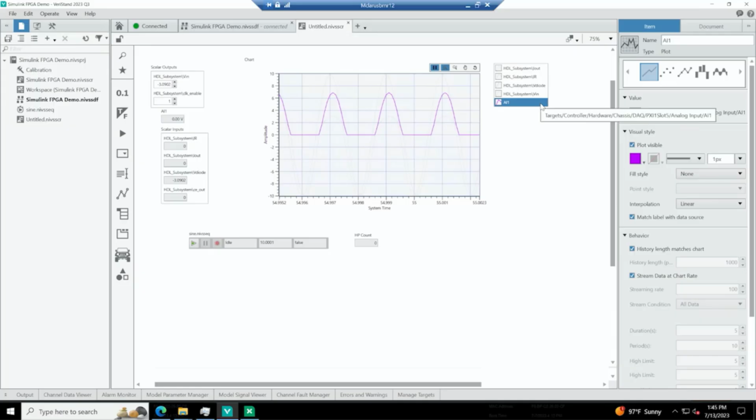with my DAC analog input channel. That's exactly mirroring the signal that I'm getting back into my CPU, which is a great sign just to show that my physical output's mirroring that. And then lastly, we can look at my diode voltage. That matches also what we were seeing in simulation.